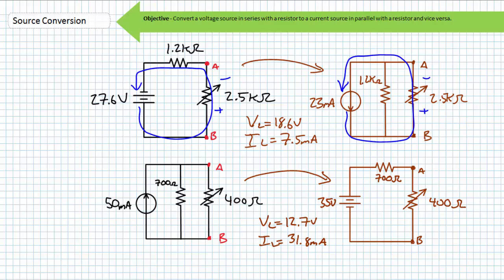We'll make use of source conversion in later circuit analysis scenarios. It's a simple and effective means of making circuits easier to visualize and analyze. Notice we applied either the CDR or the VDR when we made the conversion. If you overwhelmingly prefer one technique to the other, you have my permission to do a source conversion and make it happen. Either configuration should yield identical results.